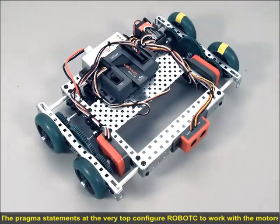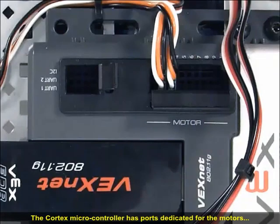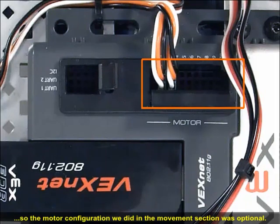The pragma statements at the very top configure Robot C to work with the motors and encoders connected to your robot. The Cortex microcontroller has ports dedicated for the motors, so the motor configuration we did in the movement section was optional.